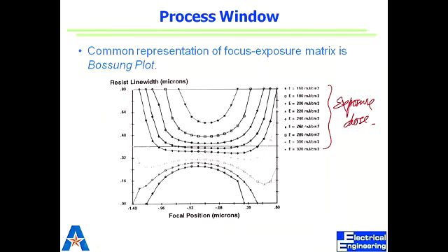You have to digest this. You need to understand this part. As a process engineer, you will not have to establish this, since it will be established for a specific lithography machine, but you might have to measure it. Given this plot, you should be able to know your process condition. Depth of focus: if you are given something like that, you need to figure out what energy you would want to use to get that feature. Of course, the height and the minimum feature size will be given. Make sense? It will be just a very small window there.